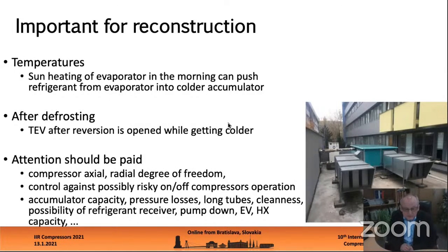Attention should be paid to compressors, axial and radial degree of freedom, control against possibly risky on-off compressors operation, accumulator capacity, pressure losses, long tubes, clean needs, possibility of refrigerant receiver, pump down, and so on.